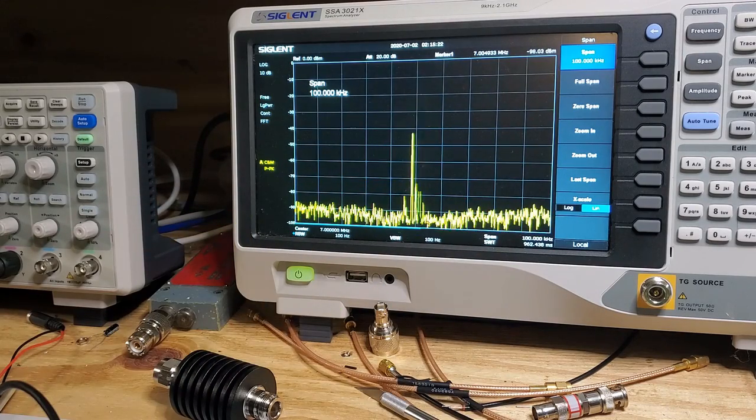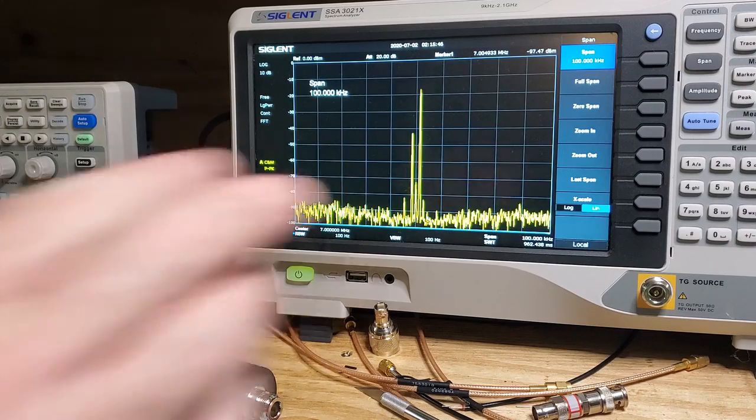So again, I've got to do some experimentation with those op-amp filters. I was using very cheap components there, so that could be the cause of it. There's a variety of different things going on. One other thing, I did order some 1% capacitors for the phase shifter. I was using 5% before, so maybe that'll make a difference. I'll do an update video later on if it makes a difference.